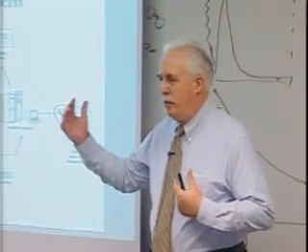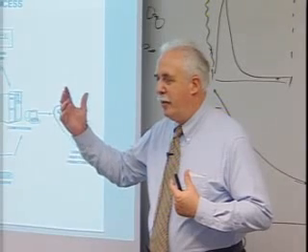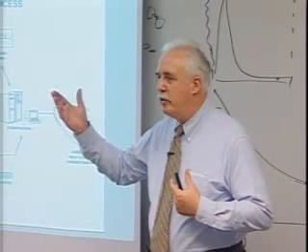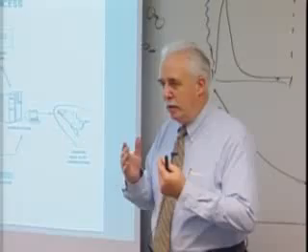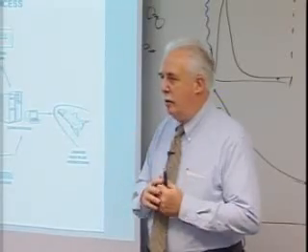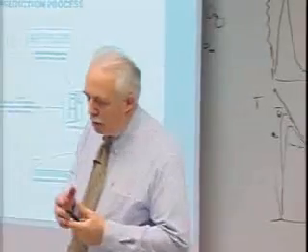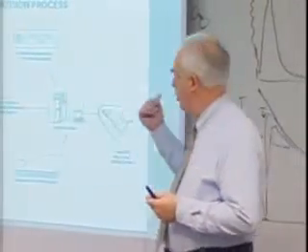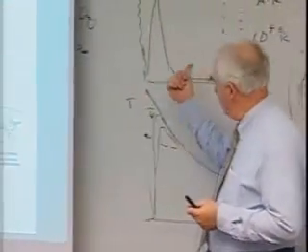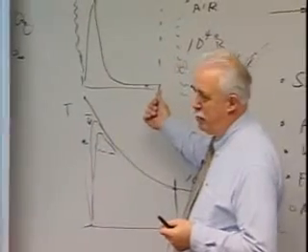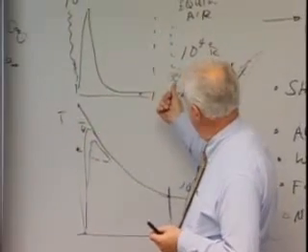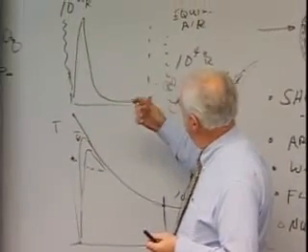If we're at equilibrium, that is, the chemistry is fast enough that you're always at equilibrium all the way through the boundary layer, you get this amount of heating. And that amount of heating included not just the conduction, but the chemistry changes going from dissociated atoms, if you want, and putting that energy back into translation, rotation into molecules.